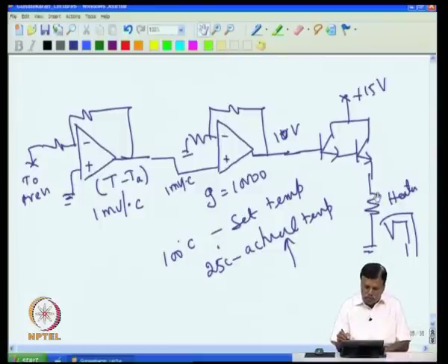That means then the heater voltage is coming down. That means once the temperature rises, then at very close range, this voltage will come down and this voltage also will come down and the heating also comes down. But at some point, whatever heat is generated by the heater will be equal to the heat that is going out. At that point it will stabilize. That is the idea of this